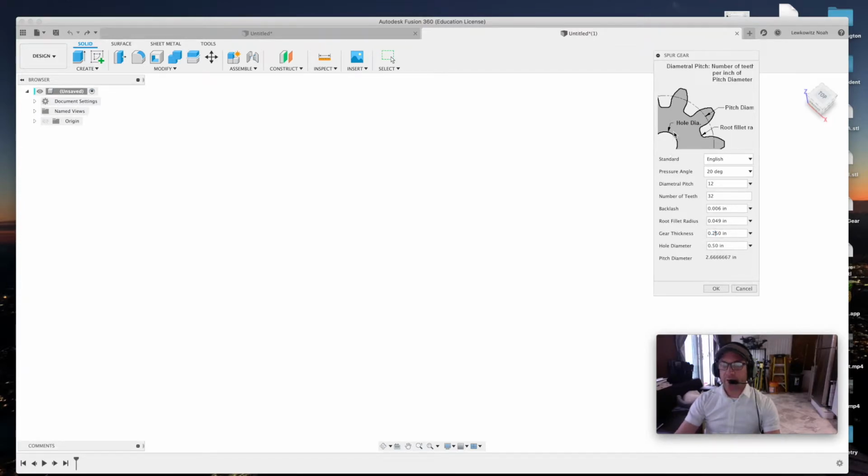And then the hole diameter, that is this hole diameter. If you type in 0 here, you'll actually have no hole diameter, which is kind of nice because then you can actually make your own later. And by doing that, you can update that hole diameter. So it gives you a little bit of flexibility. Once we hit OK here, it's actually kind of hard to change all these options. And so allowing that to be 0 gives you a bit of flexibility with the part.